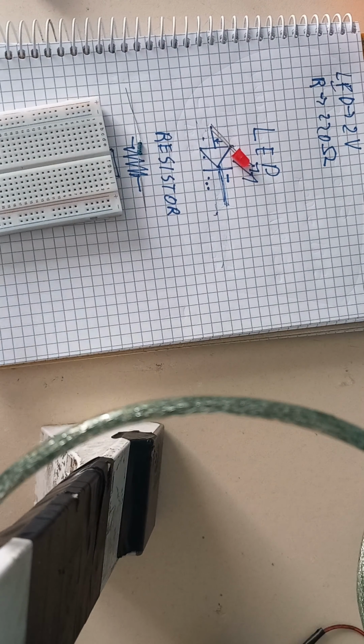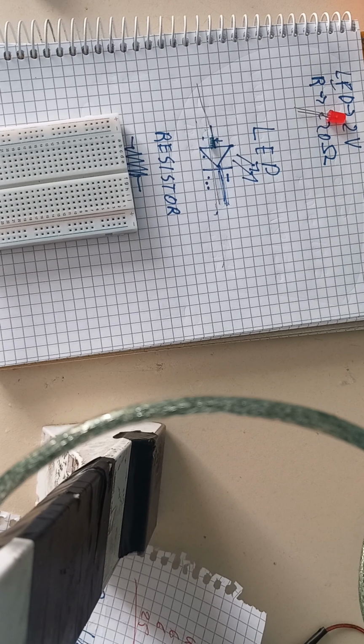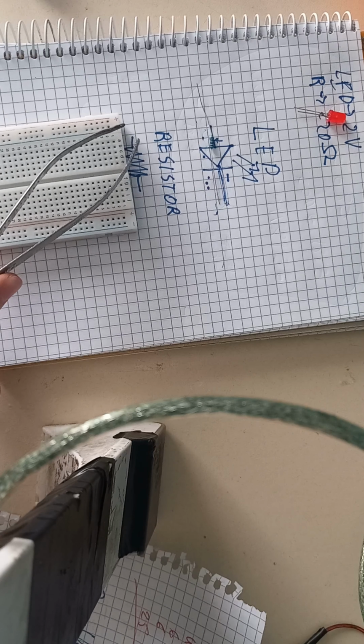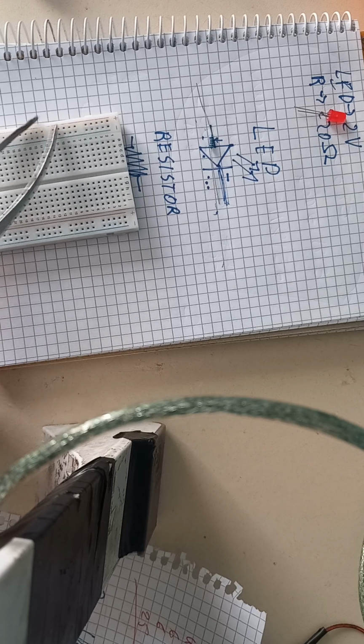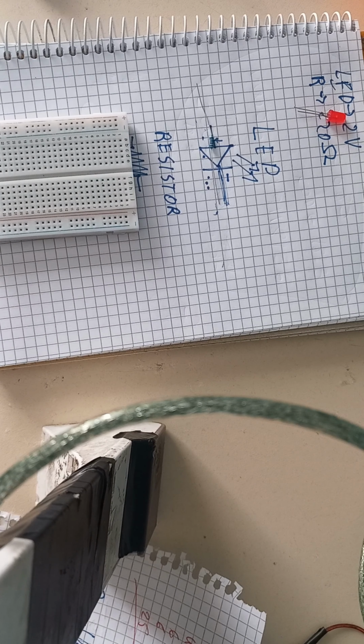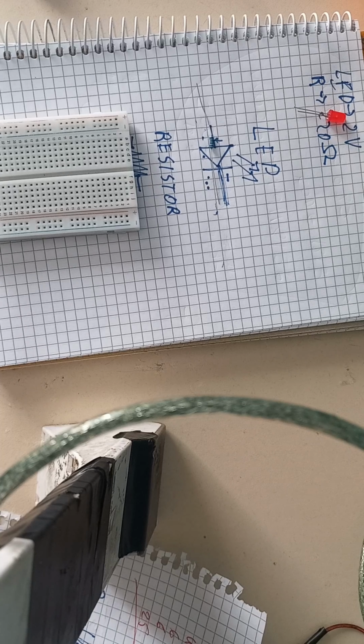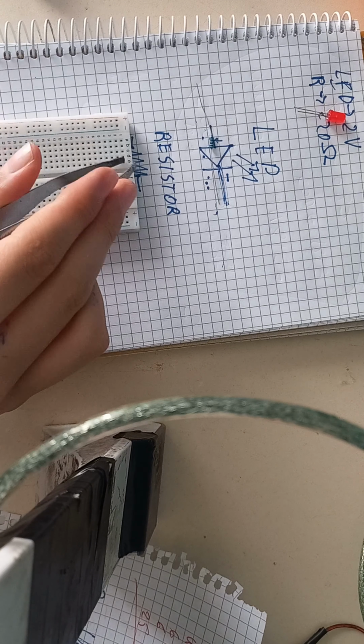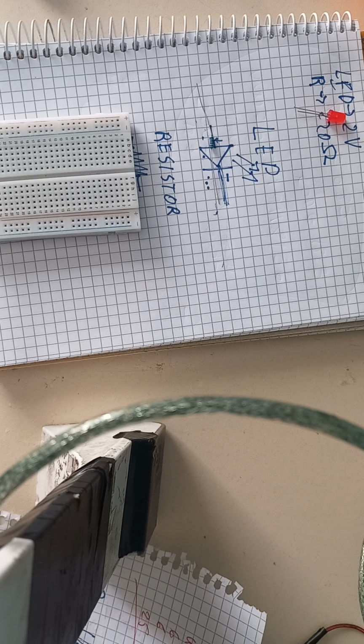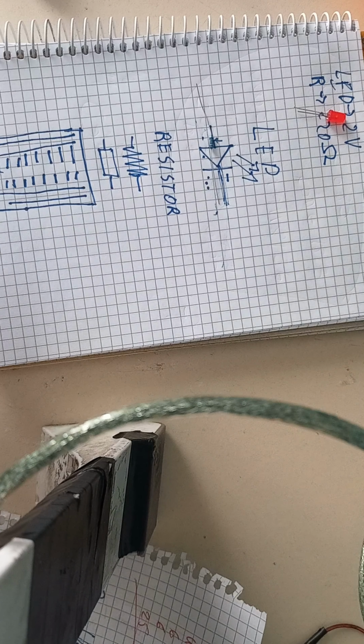Let's now explain what a breadboard does. Breadboards are used a lot of times in electrical projects. They make it easier for people to do electronics as it doesn't involve soldering. A breadboard basically has two sections, the vertical one and the horizontal one. The vertical section is mostly used for giving power to the breadboard, and the horizontal ones are mostly used to add electronic components. Let's see how it actually is.